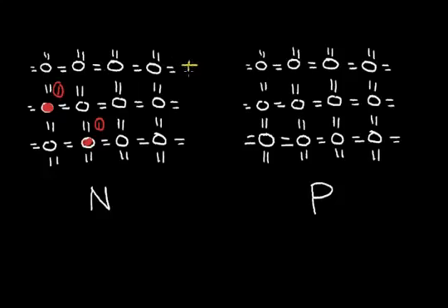Now, if I were to apply an electric field, apply a positive charge on this side and a negative charge over here, I'll set up an electric field in this silicon bar that is in this direction. And what will happen is the electrons will be attracted to the positive plate. So the electrons are fairly free to move about. And so this insulating material, because I've added phosphorus to it, now becomes a conductor. I have a source of charge that can move, and moving charge produces current.